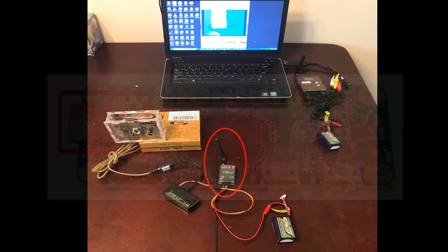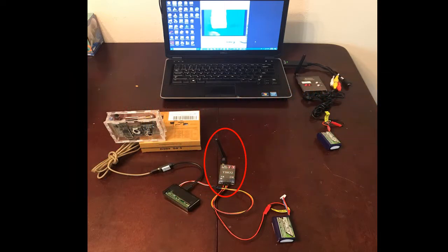For transmission, we use the TS-832 from Wolfwhoop. With a frequency set to 1 and channel set to 7, it takes the analog images from the Raspberry Pi Zero and wirelessly sends them to the receiver, the RC-832 by Wolfwhoop. The receiver is set to frequency 2 and channel 1. The video output from here comes out through AV cables, which is connected to an EasyCap converter. This converts an AV connection to a USB connection to be read into the ground station laptop and into the tracking program.